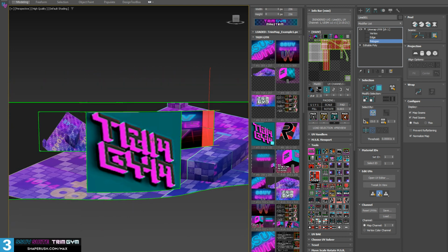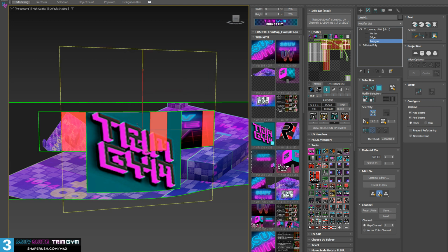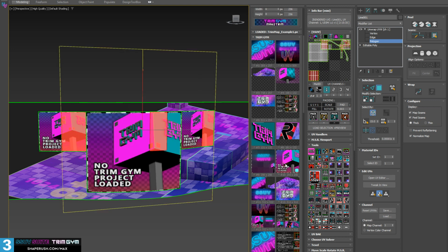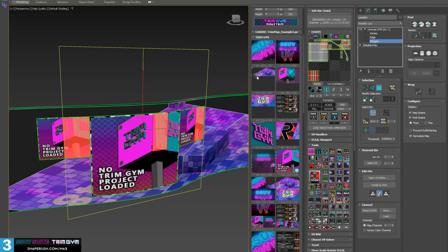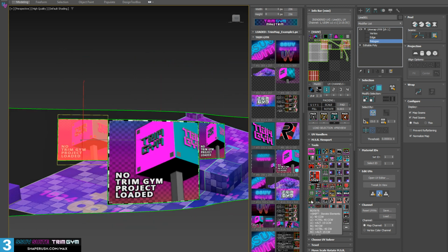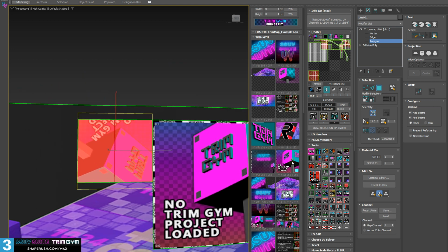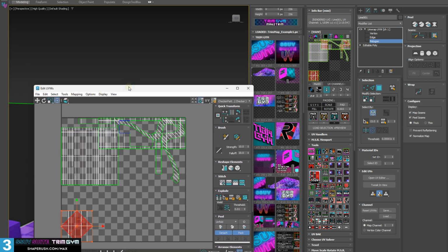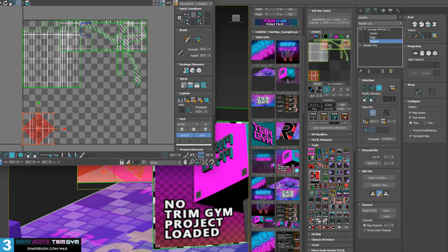If I have a face selected in different elements, then left click a trim piece, it will cycle through the elements of the faces that I selected, and then assign that section to the UV space, right? Now, if something is rotated like 45 degrees, let's get a 45-degree rotate, and then I click this, okay? It's scaling within its own, I should open this up so you can see this. It's trying to conform what is rotated to that space. And that's exactly how it's supposed to work. We have ways of fixing that, which we'll get into.